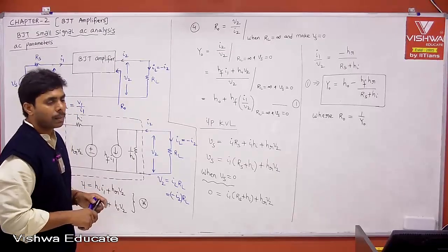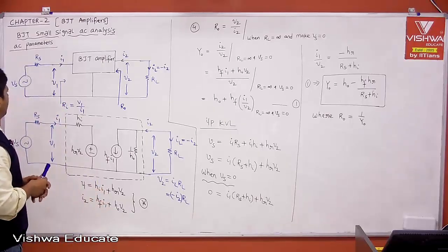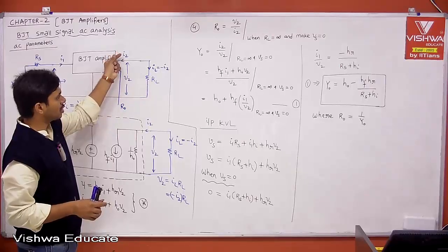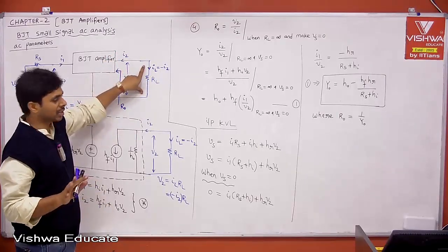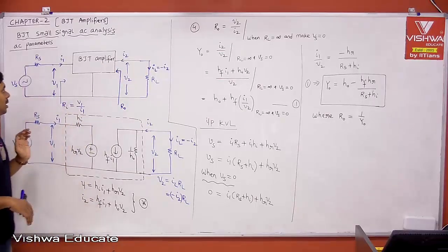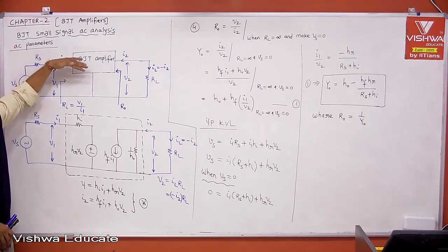Okay. Now, after this, write down as I told you. Because in this case, the load is connected, the current which is entering into your load is IL, and the voltage you are applying to your load is V2. With respect to load, V2 and IL are provided by your amplifier. Similarly, if you excite with a practical voltage source, then part of Vs we are applying to your amplifier, which is nothing but your V1. When you excite with a current source, part of Is you are going to pump into your amplifier.